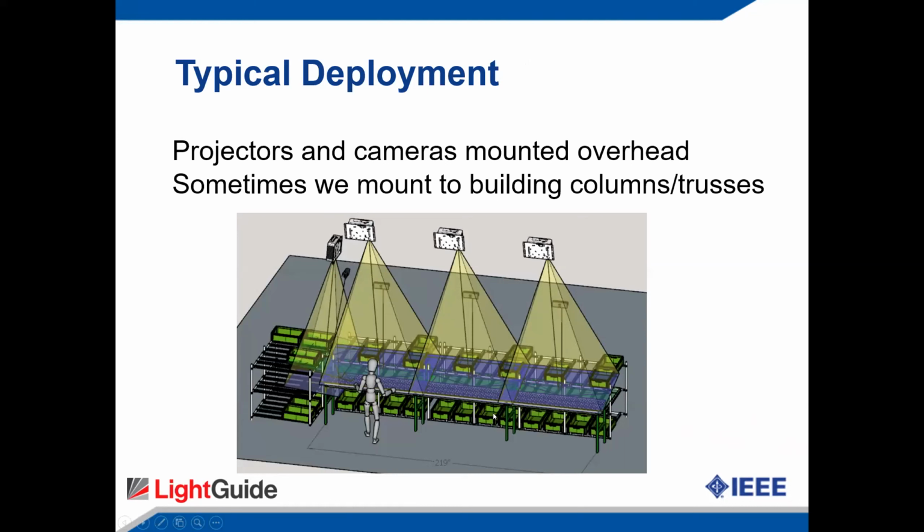We have some parts that are on a factory floor. We have projectors projecting on those racks, and we'll have cameras. I don't see my mouth, but the white objects toward the top are projectors that are projecting light, and then the darker objects down below are USB cameras that are depth cameras. They're usually using 850 nanometer infrared light, either structured light or time of flight, different mechanisms to measure depth. But they can tell when your hand is going into a bin or touching an object, and then our augmented reality can react to you doing something. So we can make it an interactive error-proofing system.